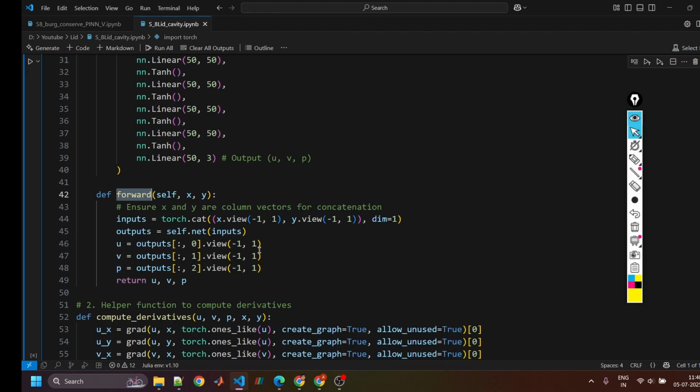In that case, we can enforce the pressure and density to be positive by making it an exponential, or you can use the square of that value, or you can also use a ReLU function on the pressure, so that it will always be positive. When we go for incompressible flows, sometimes we may get a negative pressure or density that will destabilize the numerical scheme.